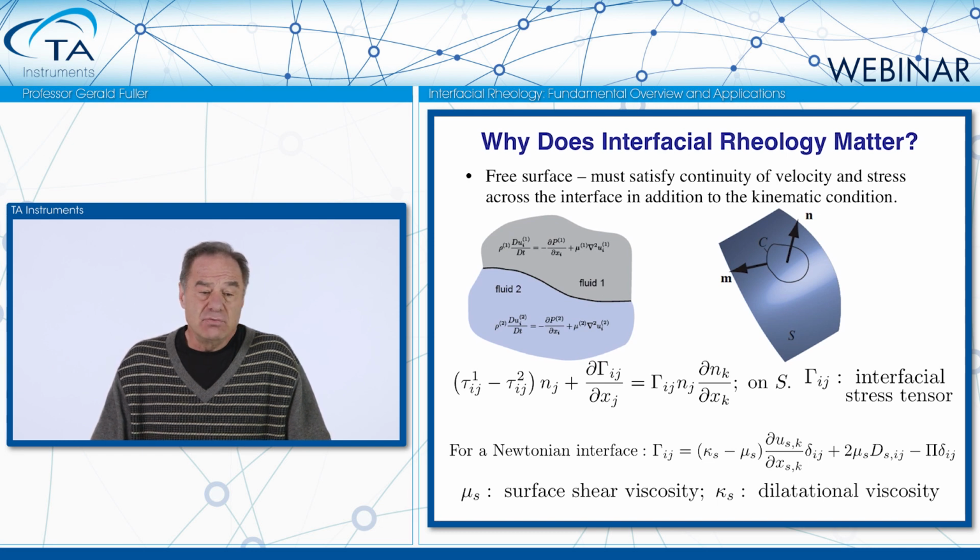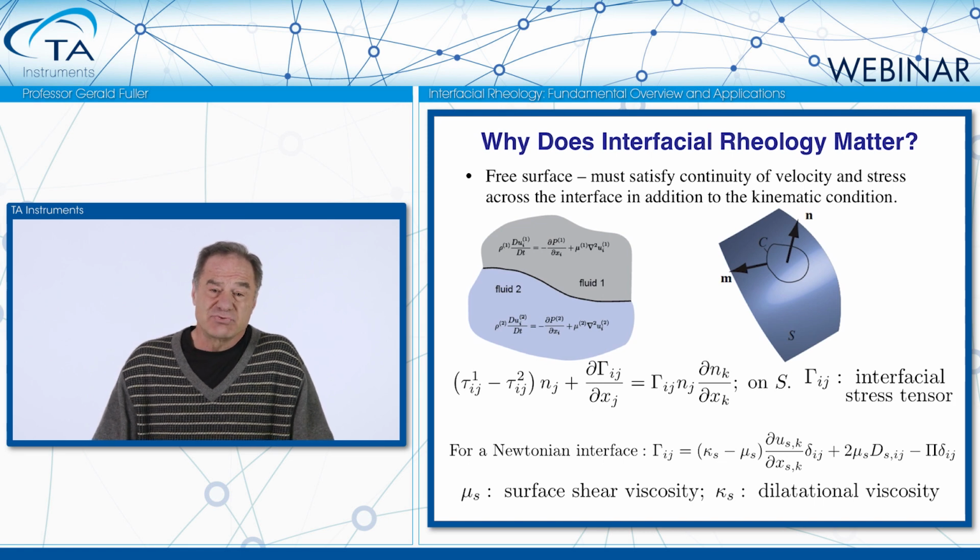You've got the two fluids, oil and water, and they are described by equations called the Navier-Stokes equations that allow you to predict the stresses in those liquids. And then you have the interface between them. And that means you need to invoke what's called a boundary condition that connects the stresses from fluid 1 through the interface into fluid 2.